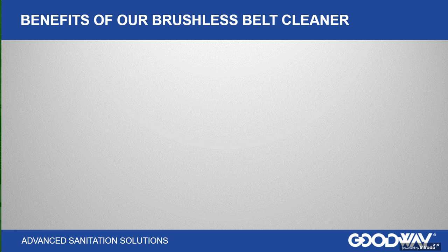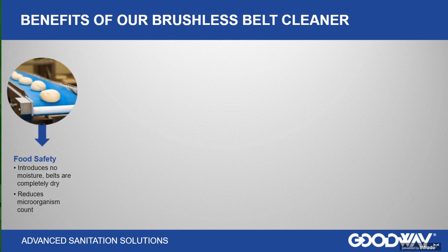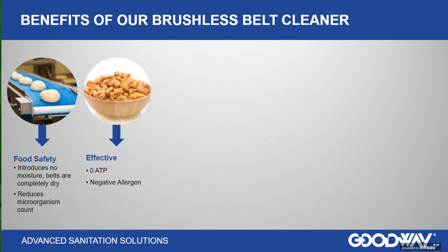So some of the benefits of the brushless belt cleaner. Food safety: it introduces no moisture into the environment. Belts are left completely dry. We also reduce microorganism counts through that heat transfer to the belt surface. It's really effective cleaning. After one pass through the belt cleaner, we'll get 0 ATP, negative allergen.